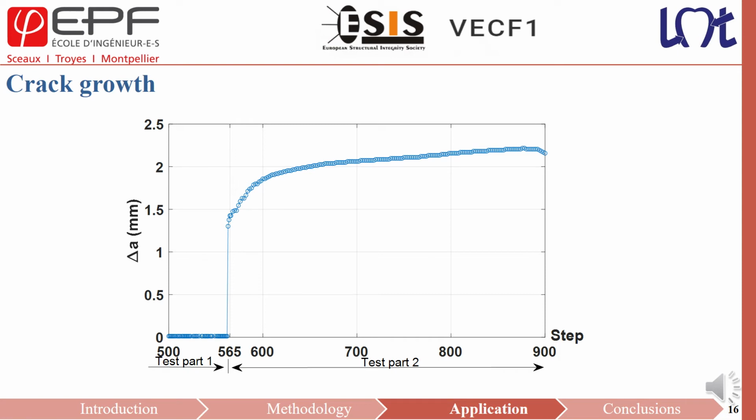Once reaching step 562, the crack initiates and propagates between the two filaments forming the edge of the notch. The notch fully opened along its length, which was equal to 3.6 mm. The displacement fields were reset because of the magnification change.